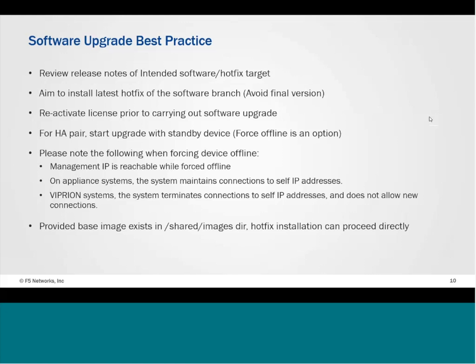They do not happen when you are actually installing the software. The validation of the license is not done during the actual install process. It's done when the configuration is being loaded. That's where the license check and service check is actually done. So even if you didn't reactivate the license and you then ran into a problem with the configuration loading, you could still reactivate the license at that point to resolve the problem. It's usually best practice to reactivate the license before you carry out the software upgrade.